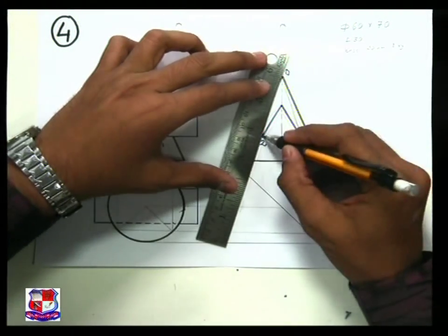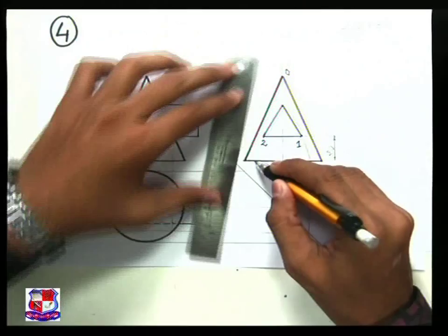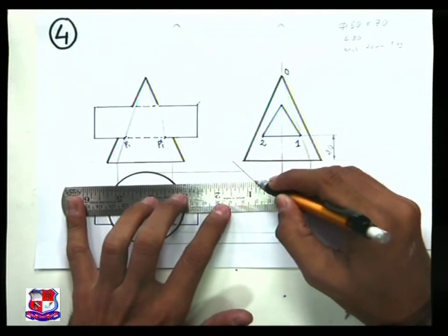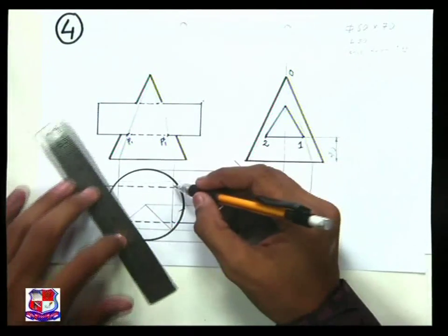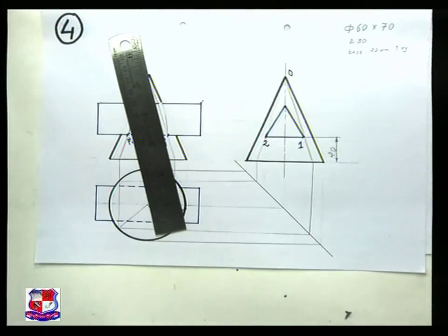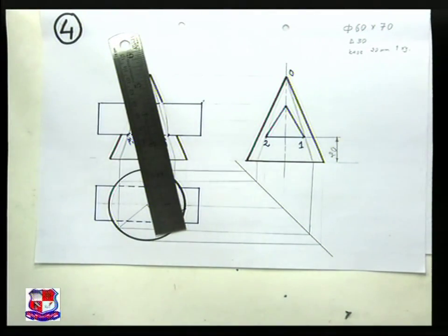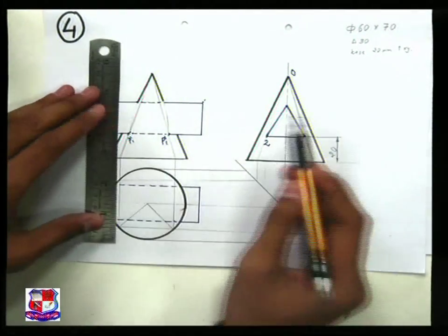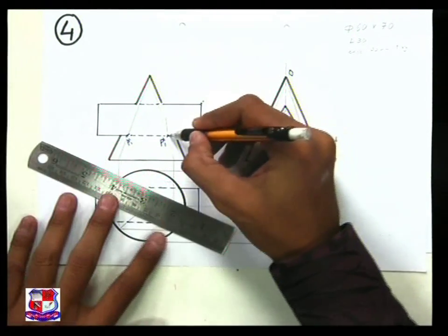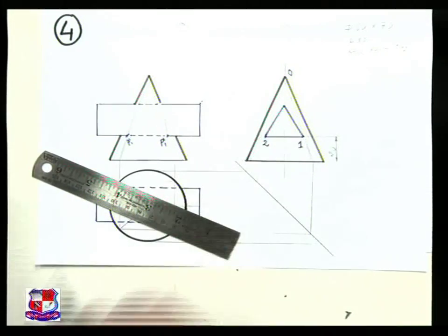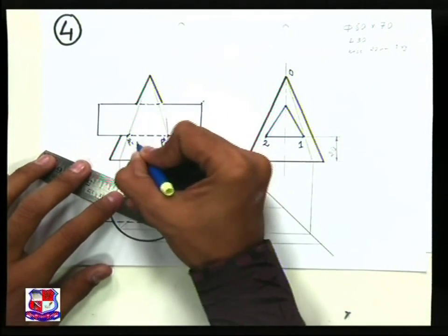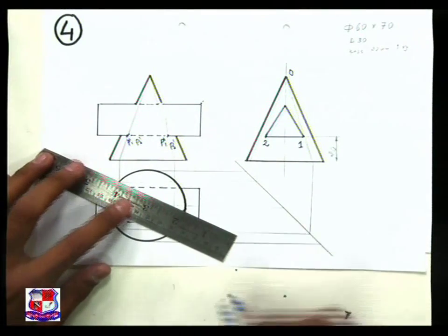Join that point number 2 with O like this. From this draw that generator, so draw horizontal lines, cut it over here, so the same generator would be over here. After finding the position of this generator, draw a horizontal line, and it will cut the same generator at this point. So point 2 also would be at the same position; points P1 dash and P2 dash are both at the same position.